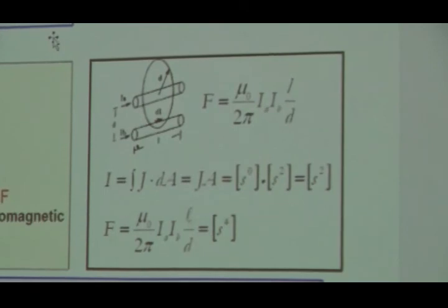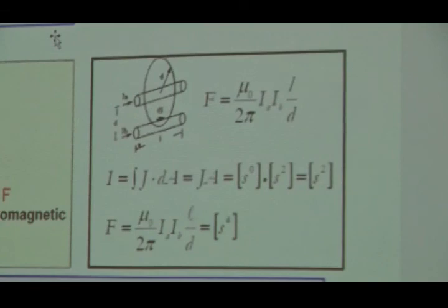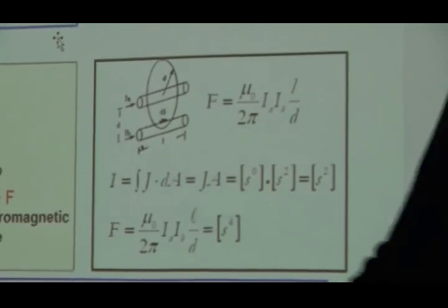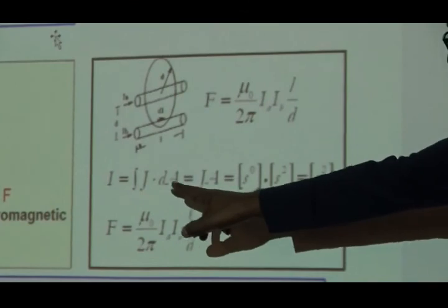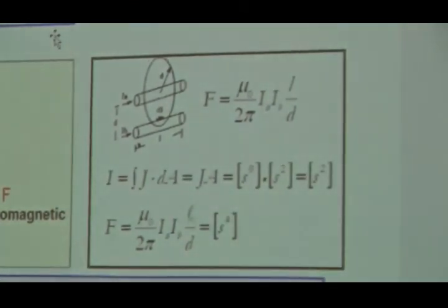So for that, what you have to know is, pay attention, that's not a big deal, and you don't see it when you took calculus. Turns out, current is the integral of current density, right? It's already density, so if I multiply by the area, I get current. So current is the integral of J times dA. If you have an elemental area and you know the current density means charge per unit area, integrate over the area, then you get your current. Now, the fact that I already got a dA, I'm making progress.